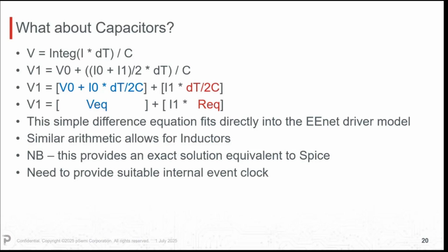As we've said before, you have to be quite careful with these kinds of approaches to make sure you don't end up inventing yourself a bad SPICE simulator, because a lot of work is going into SPICE simulators to handle error control and so on for the generic problem, and it's generally trying to solve differential equations. Here we're trying to do the least possible amount of work to give us the best possible performance, and so we have to use these approaches very carefully to make sure we don't end up having gazillions of time steps or ending up with instability.